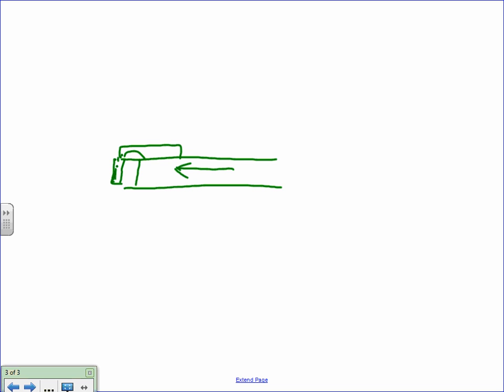This big marker is kind of crude here, but imagine a stick of EMT conduit with just some 1/4-inch holes drilled into that conduit. So the return air is coming back here, and if there's smoke coming back here, it slowly comes into here and goes into these sampling tubes, which are continuously taking a sample of the air coming back through that return duct.